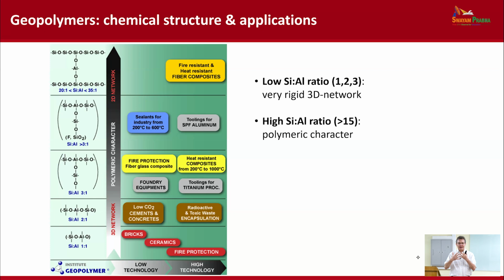And it is the secondary van der Waals and hydrogen bonding between these solid components that lead to the strength of the material. And the problem with these hydrated species is that they are not fire resistant. As soon as you dehydrate hardened Portland cement, you lose the strength, because the strength is given by these secondary bonds.